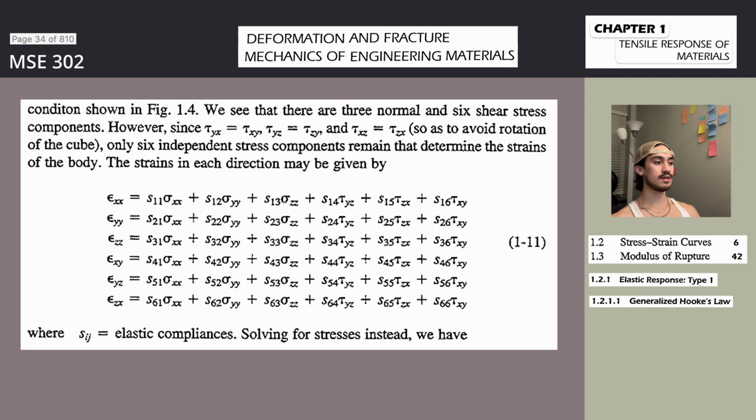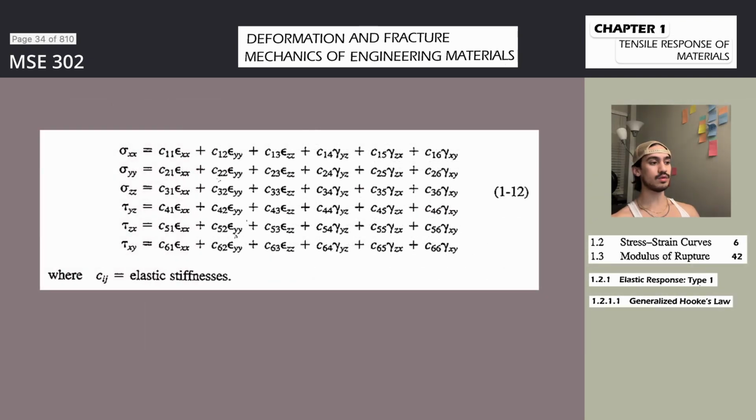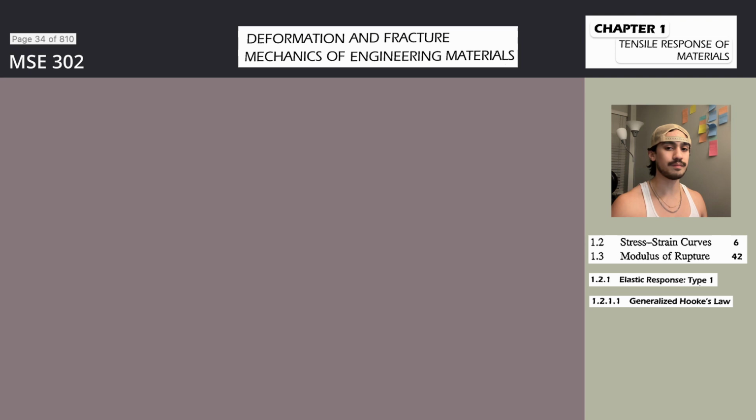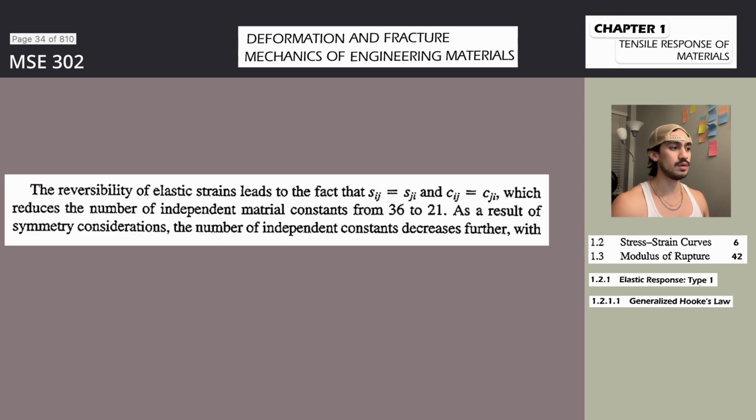1.2.2.1 Strength level in materials. It has become common practice to define several strength levels that characterize the material's tensile response. The proportional limit is the stress level below which stress is proportional to strain, according to Equation 1-7. Remember, Equation 1-7 is important. The elastic limit defines the stress level below which the deformation strains are fully reversible. In most engineering materials, these two quantities are essentially equal.